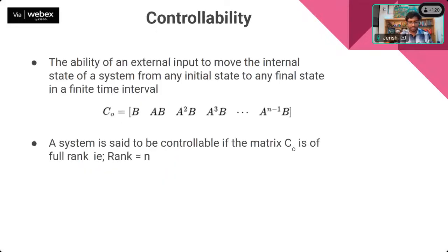Okay. So we have seen that in control systems there are two important concepts in a state space model: controllability of a system and observability of a system. The B matrix will have the information of how your input influences the rate of change of state, and A has how your state changes with respect to time. With the composite of both, there is a procedure for finding whether, with this particular input, you can control your system or not.